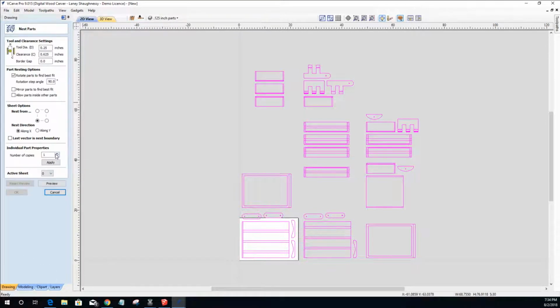the nesting feature. Now if you have Vectric VCarve Desktop or Cut2D or something like that, then you won't have the nesting feature. So you will just basically be moving these parts around, placing them on different layers, creating different layers, sheet 1, 2, 3, 4, 5, and then laying these out on layers that you can turn off and on, so it's almost like you're manually nesting them. But I'm going to use the automatic approach here with the nesting tool.